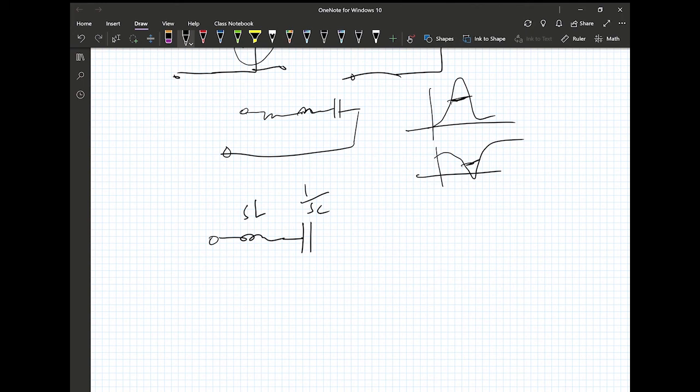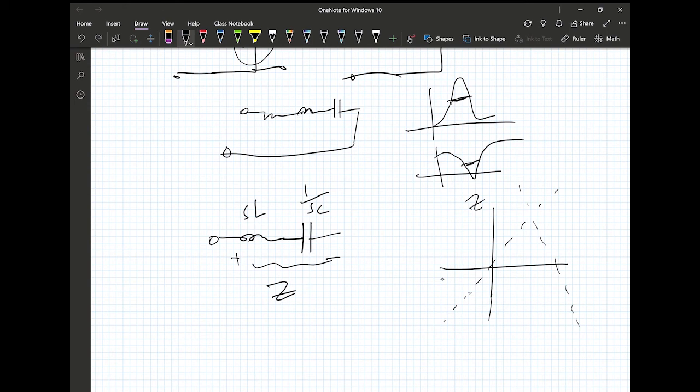right? So if I plot the frequency response at low frequencies, the impedance of the inductance is going to be, this is the impedance of this whole thing, plus Z, right? So the impedance of the inductance will dominate at low frequencies. Will be close to 0 at low frequencies, right? And then it will go higher at high frequencies. For the capacitor, the impedance will be small at high frequencies and high at low frequencies. So effectively, the effective impedance is going to look something like this.